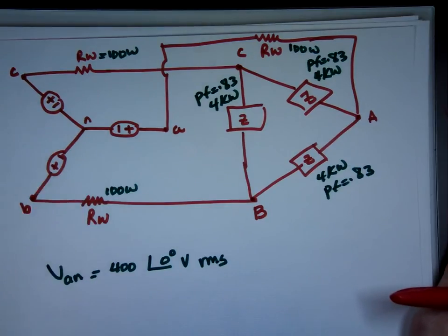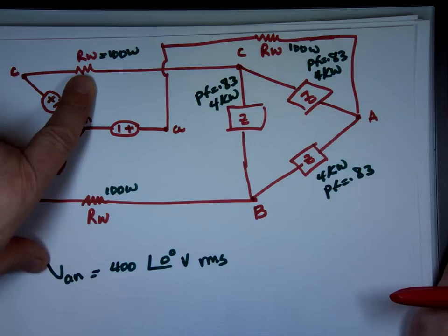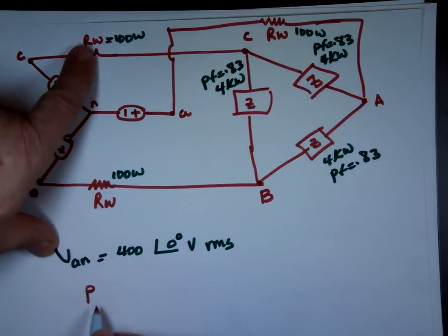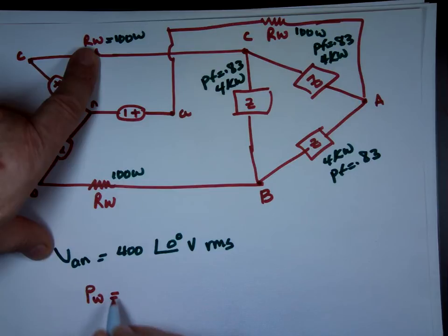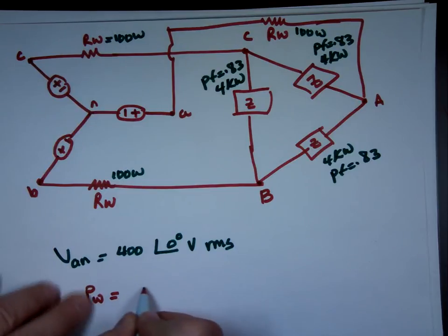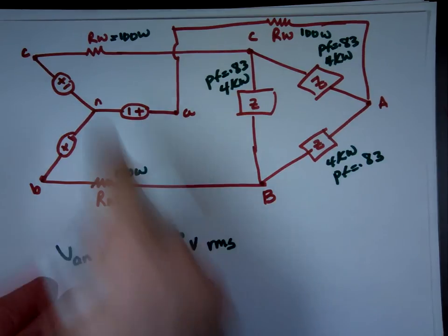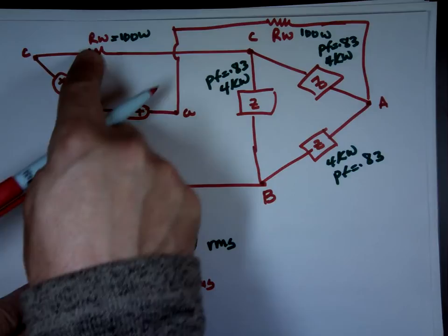So it's V times I. Talking about this one here, through the wire here. The wire is purely resistive, so it's VRMS times IRMS, and since that's a resistor, there is no phase shift between the current and the voltage, times the power factor of 1.